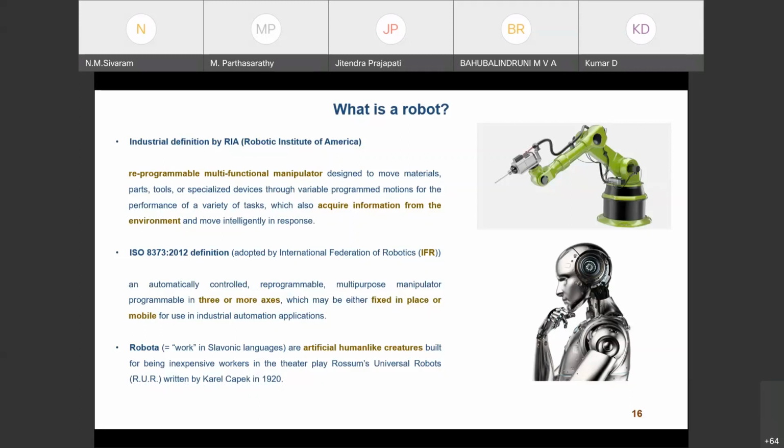But before that, it is like an autonomous machine. It can have its own movements if you are not properly protecting yourself or if you are not properly monitoring. So there itself, the hazard exists in the robot. And it is a multifunctional manipulator, so it can be used for multiple applications, like when you change the end effector, from a gripper to a welding gun to a painting spray gun, or to a small precise assembly manipulator. So based on the manipulators also, the level of hazard varies in a robot.